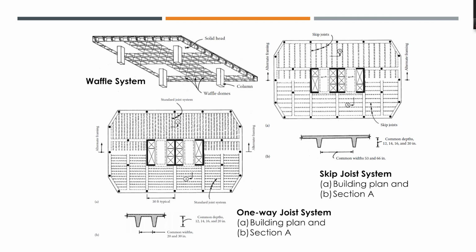And so I can just tell you roughly, if it is not a tall building, because in a tall building the depth is also an issue, and the construction speed is an issue, waffle slab is the best if you want long spans and minimum columns, because you can go up to about 12 meters that long without any columns. So waffle slab has the ability, because you can make it deep with least weight. It gives you the least weight and long spans, so you can reduce the number of columns a lot and give big spaces.